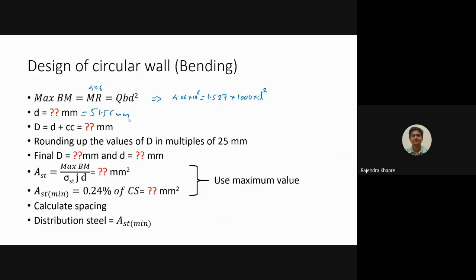This is also an indication that your wall is designed on a very higher side. So 150 is not required; 51 is sufficient. In the actual tension also we have seen the permissible stresses are almost more than double. So this way you can come to know that your structure is oversafe, and you can redesign it if required. Anyway, let us go ahead.